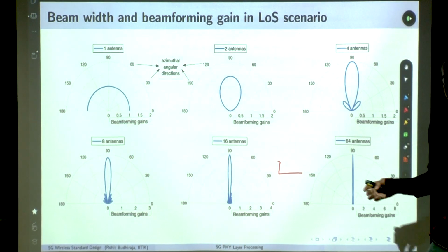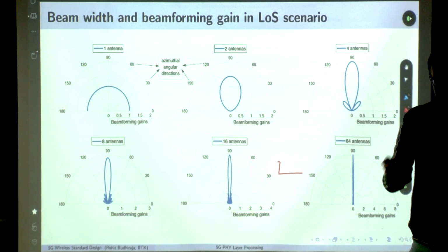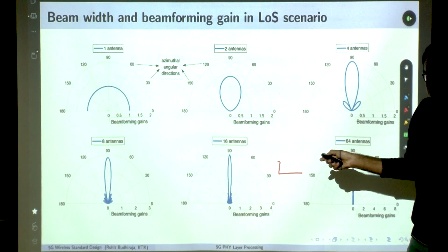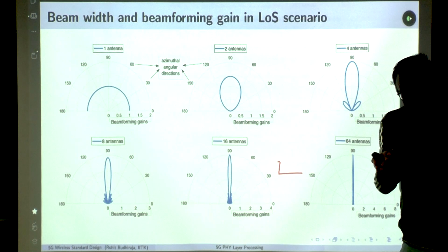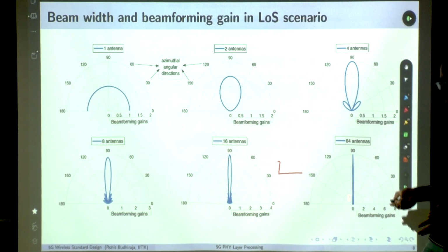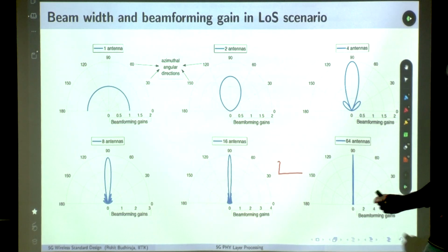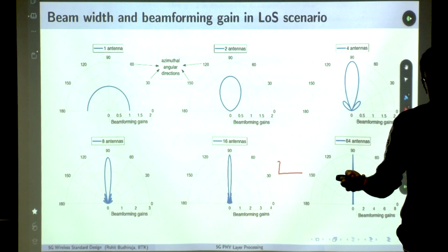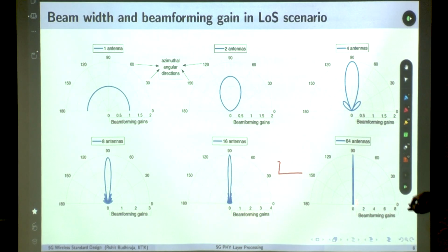We have two antennas, you precode them. Precode them with some general information. What happens? The signal is getting aligned and is being transmitted in a particular direction. What happens if there are 64 antennas? You have basically a very sharp beam. But you want this signal to get broadcasted, not to have a signal like this, because then a user over here will not be able to see the signal.